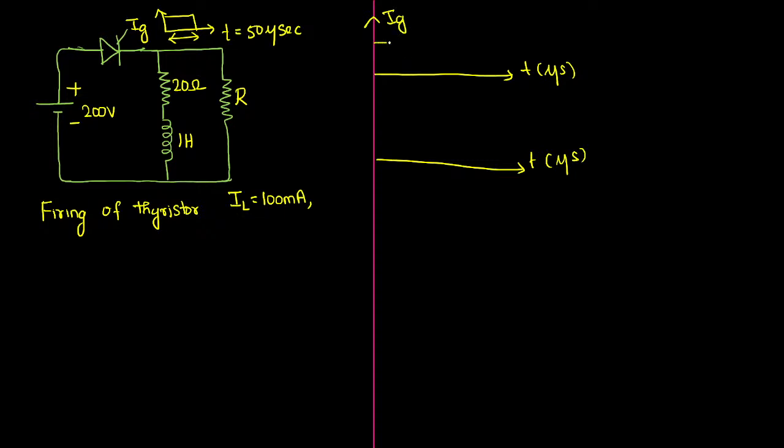For an example, you have started injecting the gate current here. What will happen? Current flow through the anode to cathode will start increasing. You all know, slowly it will keep on increasing. When the SCR turns on, current will be increasing slowly. Current flow through the SCR is increasing. SCR will turn on when this current crosses what? Crossing the value of latching current.